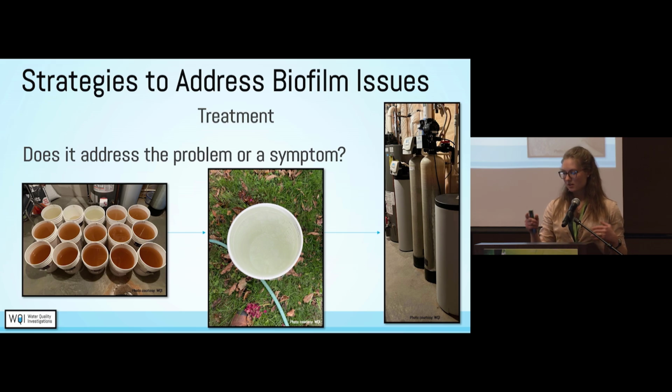When we went to their home, we did a bucket test. It looked like, yeah, you have an iron problem. Then we did an interesting thing by pumping the well for 2 hours. The bucket that you can see in the middle is what was produced by that. So it was telling us that their source might not be the problem. We discovered later there was a lot of extreme corrosion in their casing, and that was causing this discolored water. So after treating the well, they didn't necessarily need that iron treatment equipment.